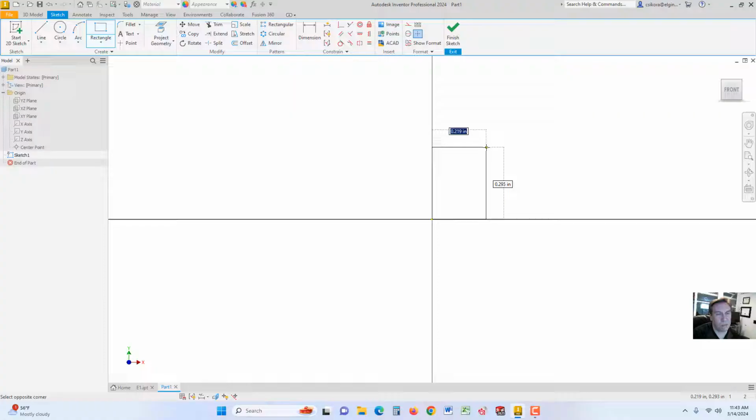All right, now as I move this to the upper right, I'm not clicking anymore, I'm just hovering, moving my pointer to the upper right. And you can see parameters appear, like in blue we could see this 0.321. Well, we want this to be 3 inches wide, so you can just type in 3. You don't have to type 3.00.